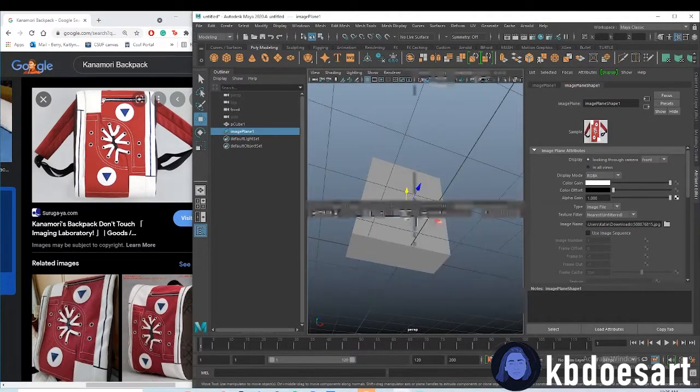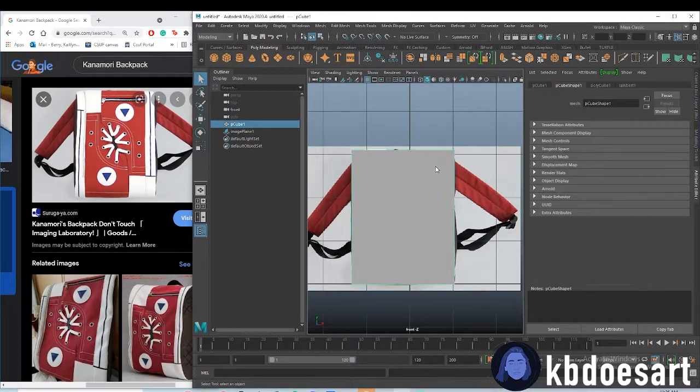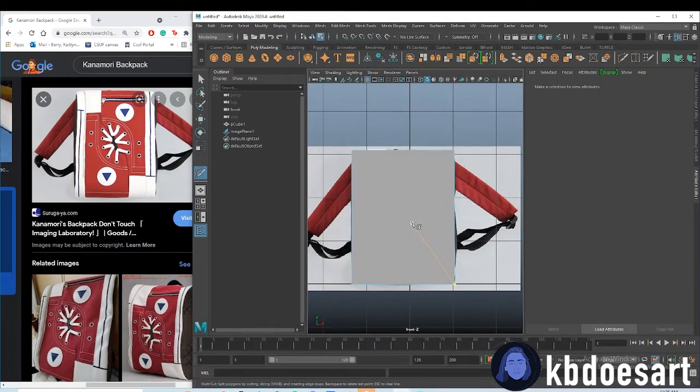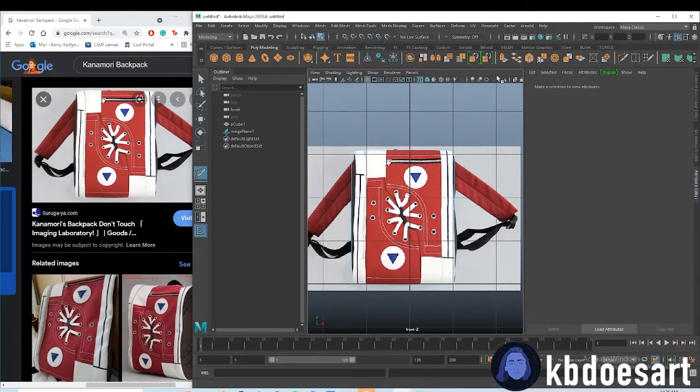All right, let's add some divisions. So hold shift, hold right click, and then go on over to the multi-cut tool. All right, our multi-cut tool we're going to use a lot. So I think first, let's go into wireframe mode. And then you're going to want to hold control and you'll get these fun little rings. That means it's going to split our object fully around.